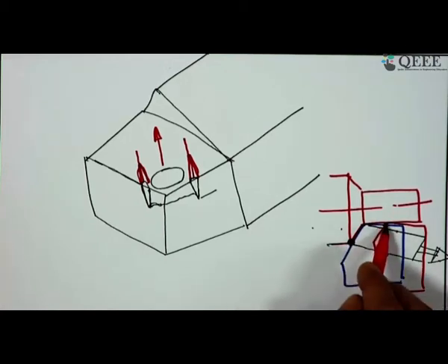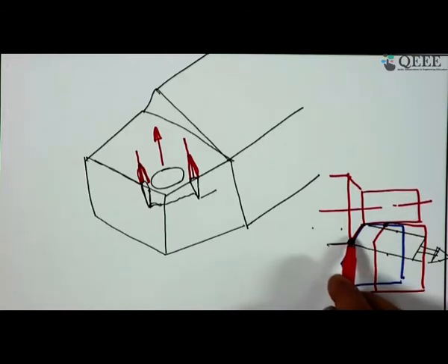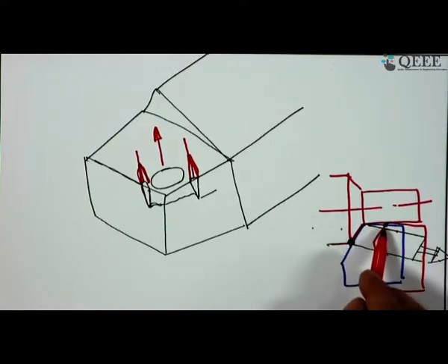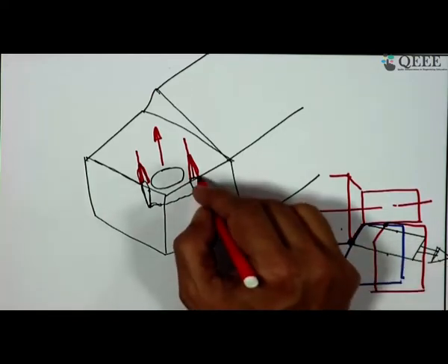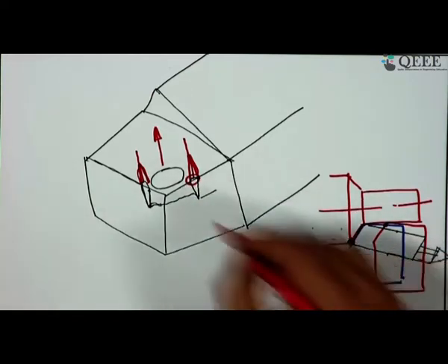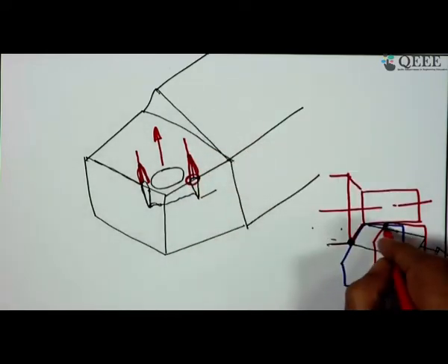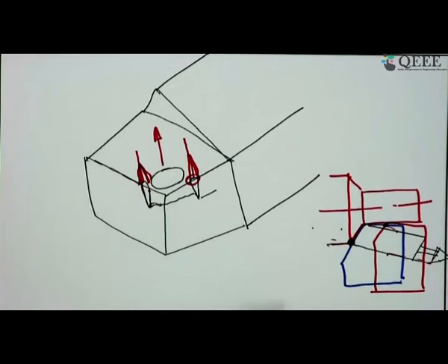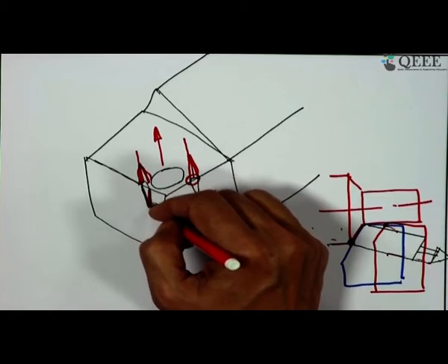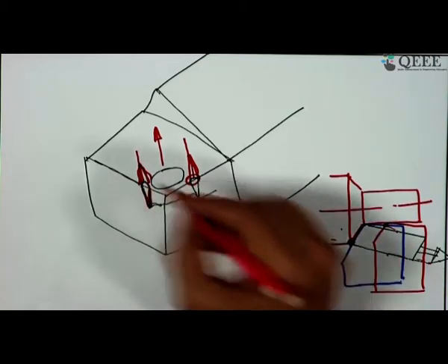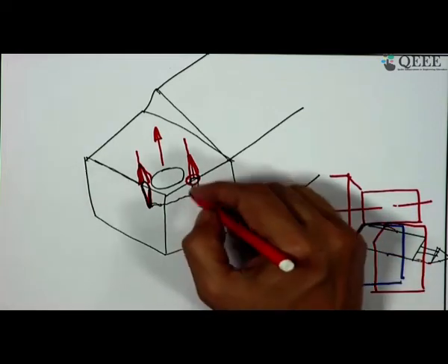of the sharp point on the uncut material, and this is the finished material, this is the transient surface, this is the edge of the original uncut material, raw material, this is the finished surface, and this is the transient surface. So, along the rake you have a sliding wear mark, along this auxiliary side you have one more sliding wear mark, and down the auxiliary flank you have the V notch of the auxiliary flank. Here you have the groove, that means the knife starts cutting, and this is the notch on